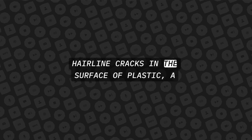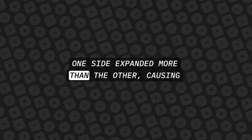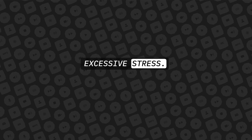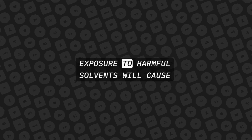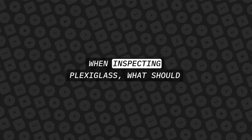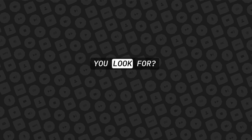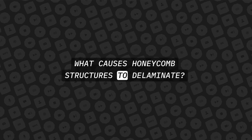Hairline cracks in the surface of plastic, a form of heat damage caused by uneven heating. One side expanded more than the other, causing excessive stress. Subjecting plastic to large stresses and exposure to harmful solvents will cause crazing. When inspecting plexiglass, what should you look for? Crazing and discoloration. What causes honeycomb structures to delaminate?